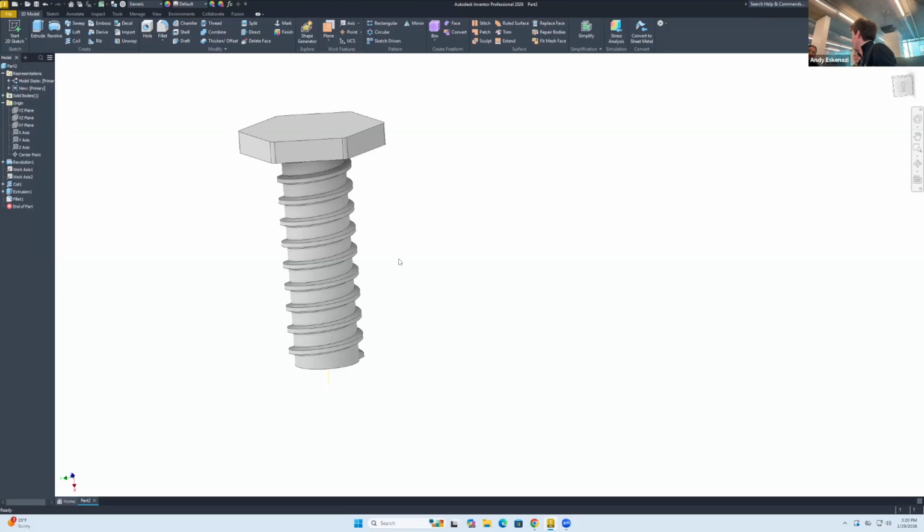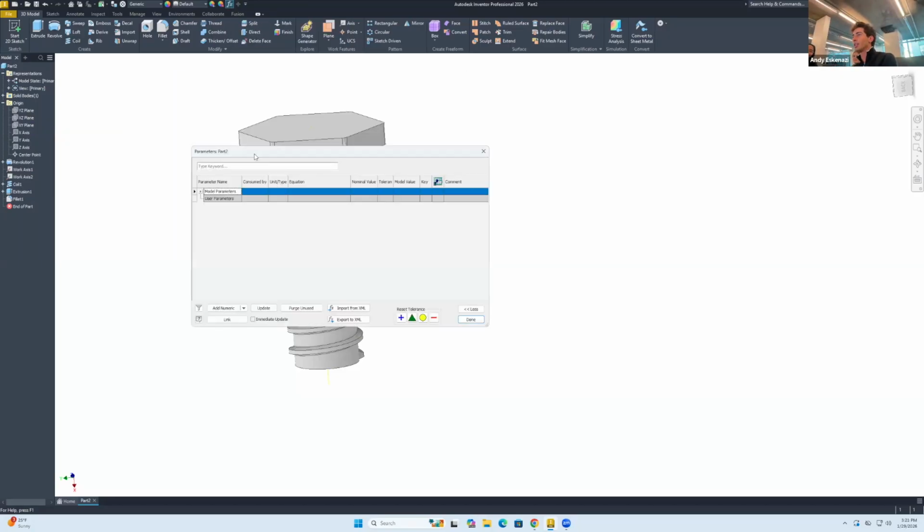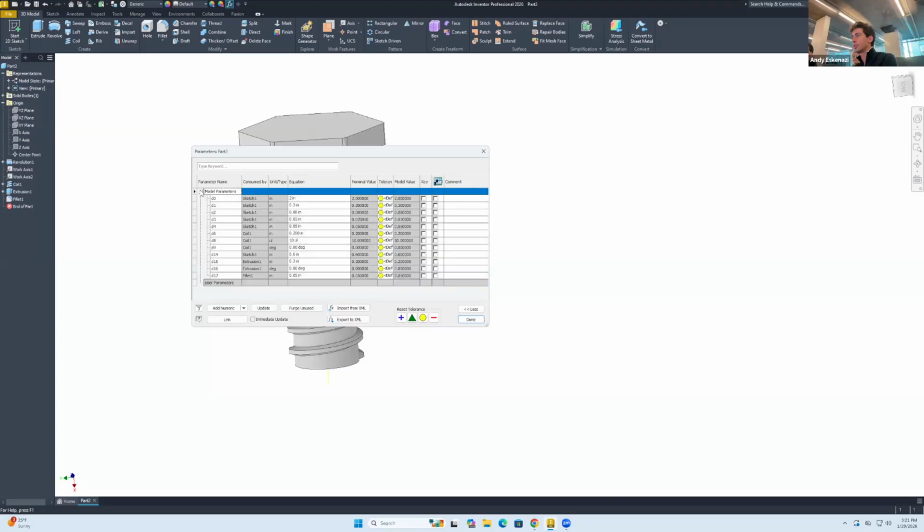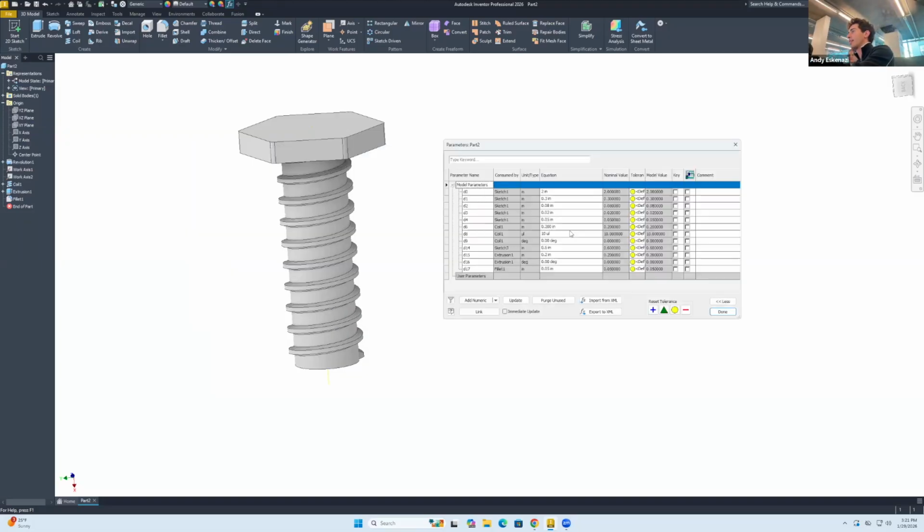Thank you for bringing that up, because let me show you. So the way you do it is you go here to this little FX command in there. So let me click. And what you can see in FX is that it consists of all of those different sketches, properties, even the colors. It's all encapsulated there. It's difficult to see what they all correspond to, but we can create parameters that you could say, right, I want the height of this to be 20, and that's going to be parameter A. I can reference that as parameter A right there.